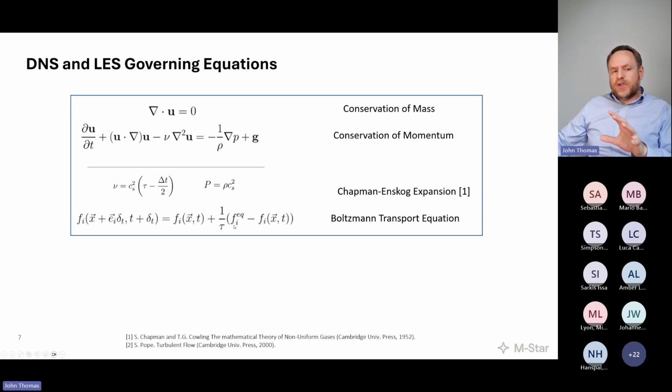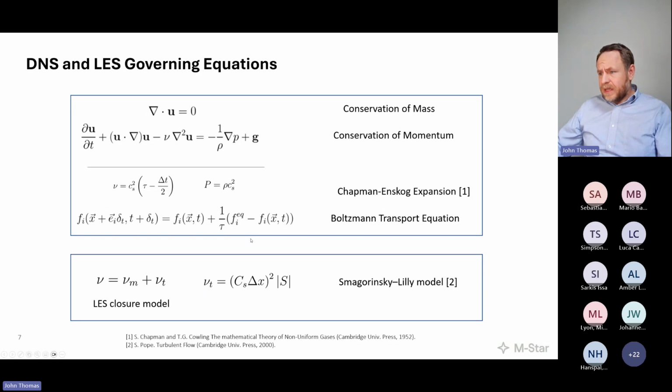We're not solving the Navier-Stokes equations using LBM. Nobody's solving the Navier-Stokes equations. If we were solving the Navier-Stokes equations, we'd be giving lectures at universities and receiving prizes. Everyone in this field is approximating solutions to the Navier-Stokes equations. And the tool we use to approximate a solution to the Navier-Stokes equations is the Boltzmann transport equation, solved in a way that recovers Navier-Stokes, again by linking viscosity, relaxation, and pressure to density, the lattice velocity, and the speed of sound. And this has been discussed in the literature for the past 30 years.